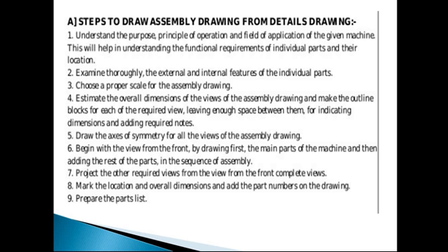So like this, first of all we require to imagine which parts are required to add at which location by observing the dimension, because sometimes there are some kinds of holes, some kind of stud is there. So if dimensions are matching this hole and stud, then definitely this stud is going to insert into this hole. So like this we require to make some kind of permutation, trial and error. By observing this we are going to do an assembly drawing. So after this number of trials we require to take some front view, top view and side view.